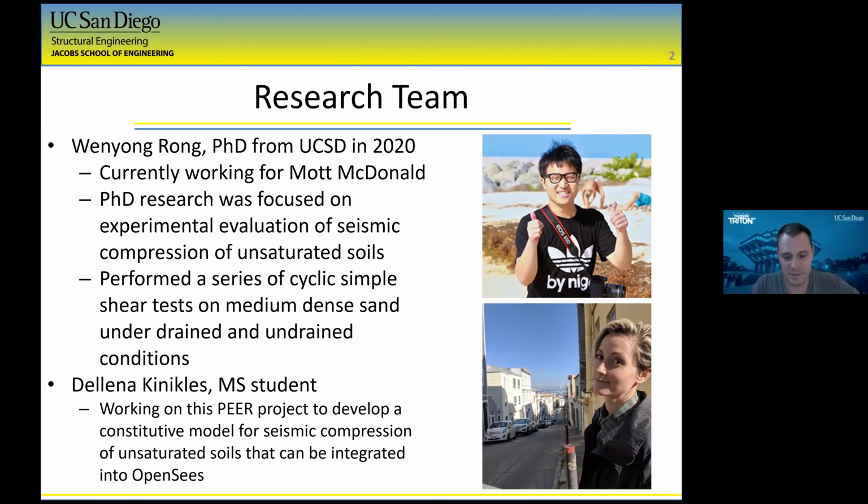So it took a little bit of time to recruit a student to work on this project, but Del Canicolas is a master's student at UCSD. She started working on this project this summer. She's getting up to speed, and we're working on creating an effective stress-based constitutive model for unsaturated soils where we're able to predict the evolution of seismic compression. Our goal at the end of the day is to try to integrate this into OpenSees.